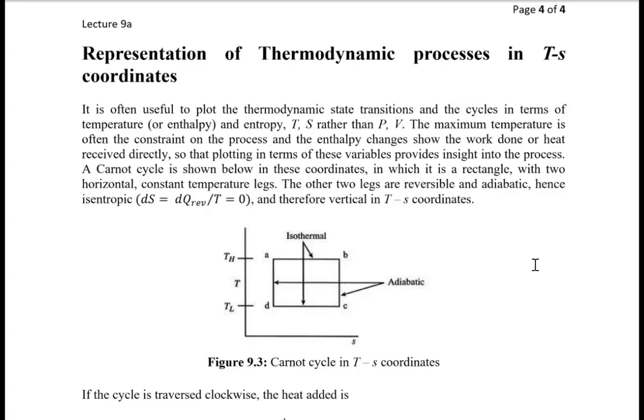Representation of the thermodynamic process in TS coordinates. Up till now, in our thermodynamics lecture, we were considering mostly the PV diagram. And while we were considering the PV diagram, we said the area under the PV diagram is equal to the work done. And that was the importance of the PV diagram.